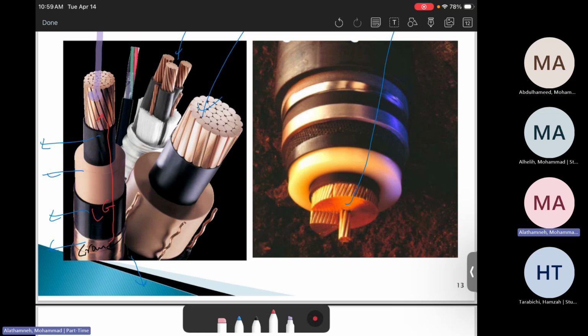If there is some fault going on or something wrong, we don't want that fault to go out to the people, because these underground cables will be under or very close to the people living there. If there are faults, we don't want that fault to go to the surface of the ground. People in the cities could be electrocuted, which is dangerous. So we want the fault to happen only inside the cable. Then we send maintenance to fix the cable. We don't want severe damage, or to kill or endanger people.